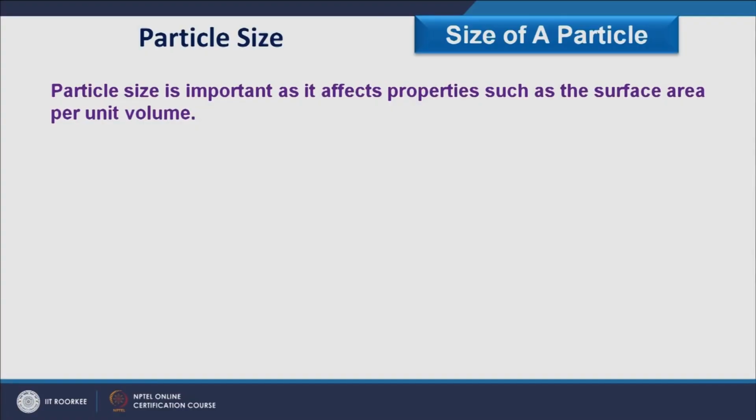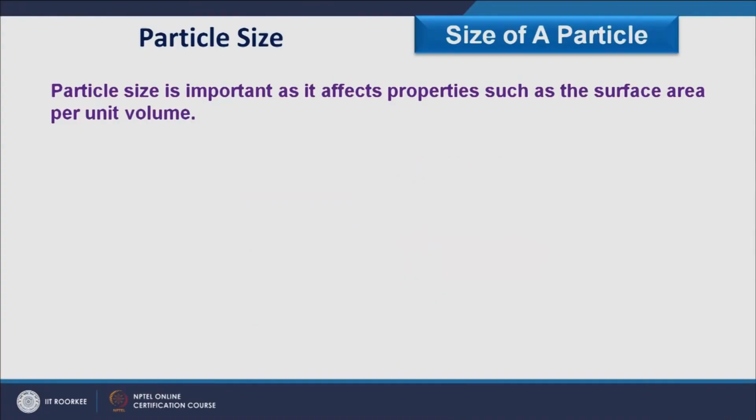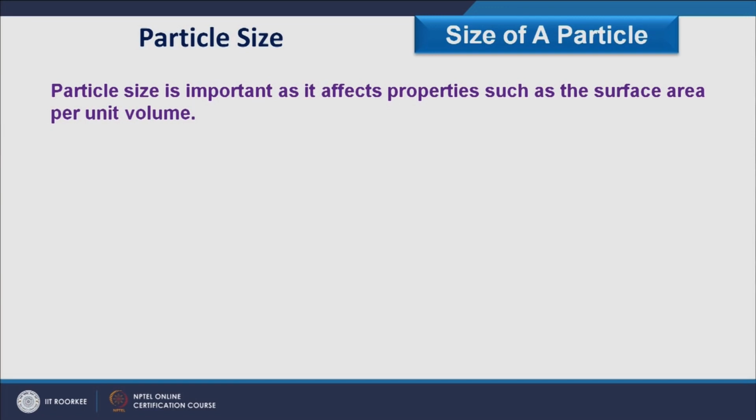When we measure the particle size, the question comes: why am I measuring the particle size? The particle size is important as it affects properties such as surface area per unit volume. And if you remember the last lecture, we discussed that particle size affects properties which are directly related to the success and failure of the product. So therefore it is important to measure the particle size.